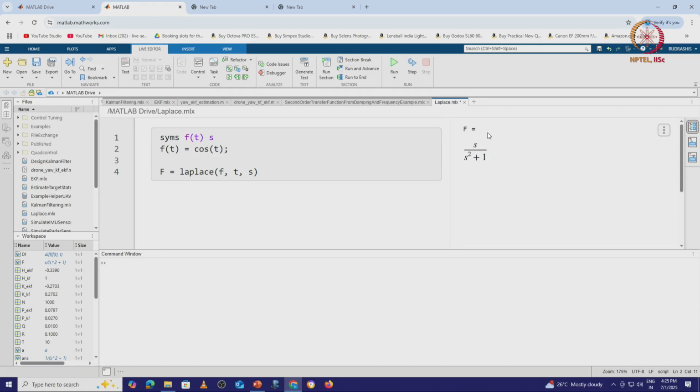So you can see that when you have this particular command Laplace, and the function is specified, then you can transform the function from its time domain to s domain counterpart. If the functions are not evaluated by Laplace, or the function cannot be specified, or the command Laplace cannot transform it properly, then it will send back one unevaluated call.